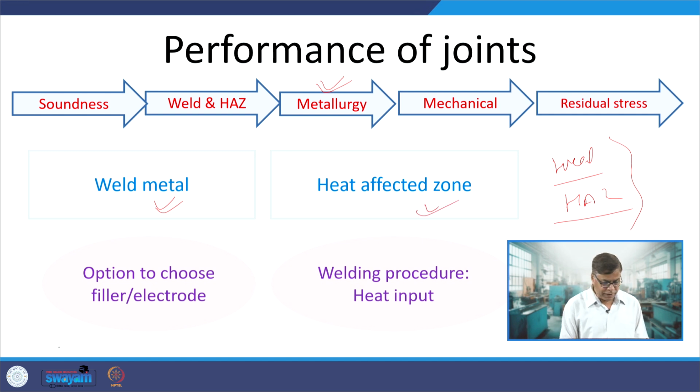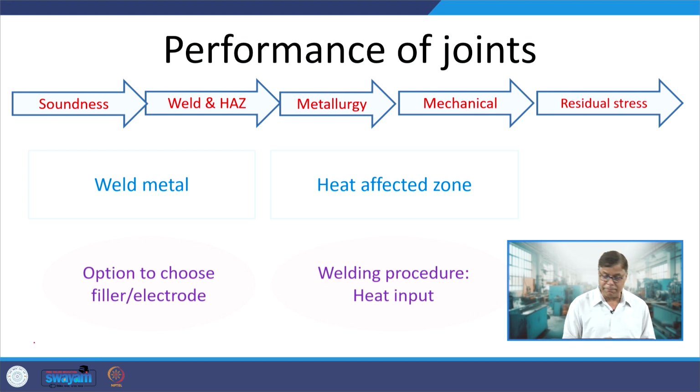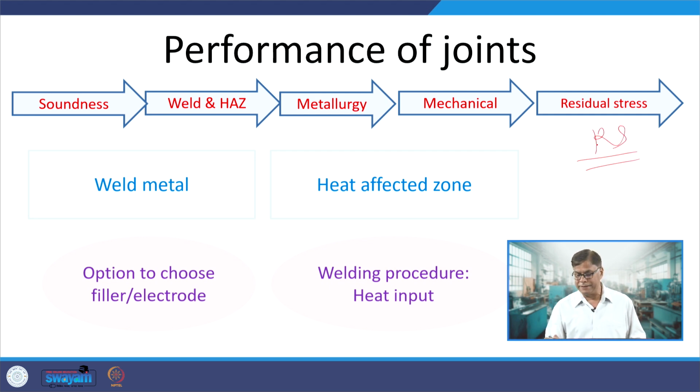For a given microstructure, we will get one set of properties, and if, due to controlled heating, cooling, or post weld heat treatment, the microstructure is altered favorably, then our mechanical performance will be enhanced accordingly. In addition, we may have the desired microstructure and mechanical properties, but if residual stresses develop in the weld joint, that will lead to increased distortion tendency and reduced mechanical performance, in terms of reduced tensile load and reduced fatigue performance.